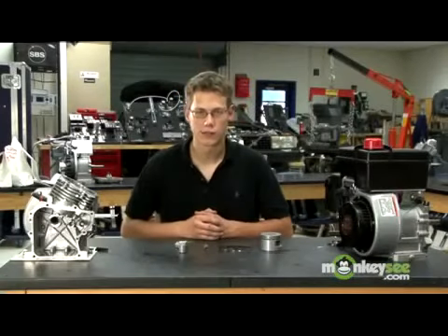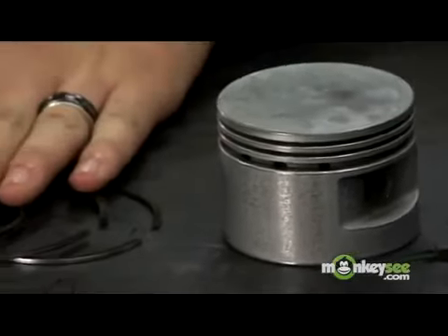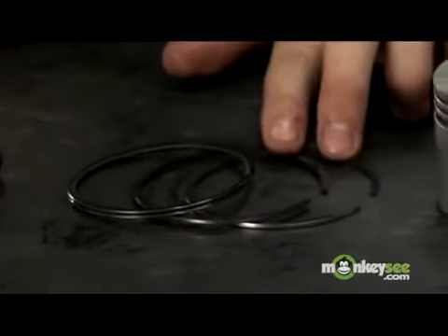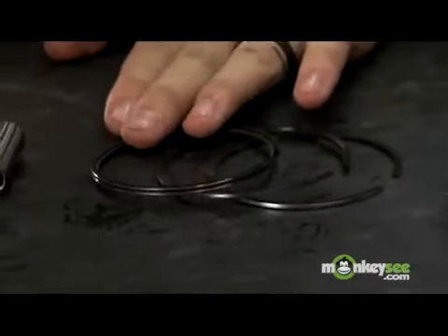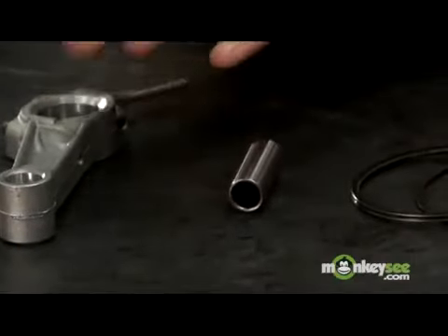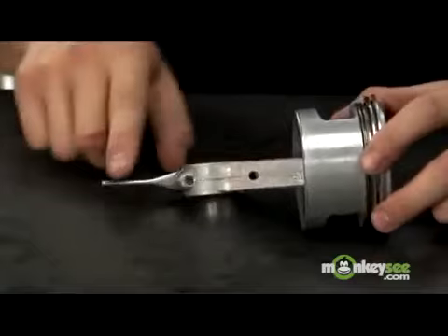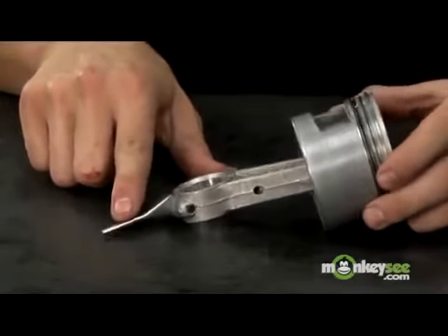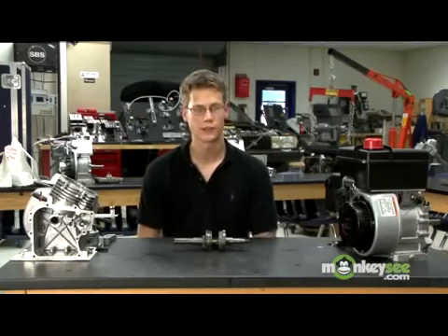The piston consists of 4 main components: the piston head, the piston rings, 2 of which are compression rings, and 1 special ring is used to hold oil against the walls of the cylinder, called an oil ring, the pivot bushing, and then the piston arm. And attached to this arm is an oil thrower, which is used to disperse oil inside of the crankcase, maintaining lubrication throughout the system. The second component I'm going to illustrate is the crankshaft.